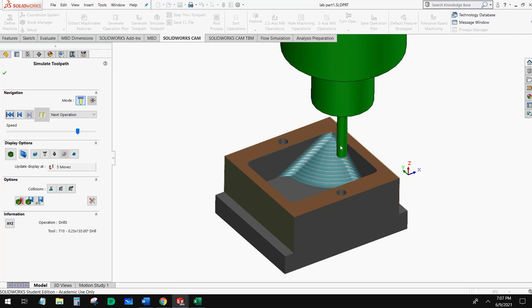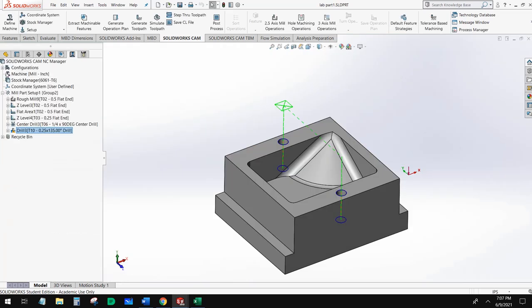And again, we're going to add some operations to this so that it pecks as opposed to continuously drills. And we're going to alter our depth on this, and I'll show you exactly why in just a minute. But for now, this looks good. And then finally, we've got all of our machining done. What we want to do now is to go ahead and face this all off.